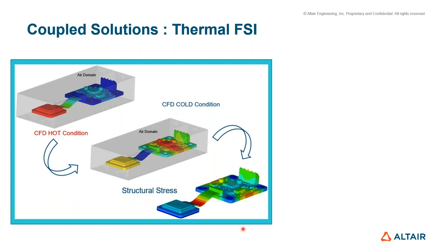Here you see I have a CFD model which has an air domain, and then there's a structure of the PCB board connecting with certain cables around the fingerprint location where you want to scan it. Now, this goes through a CFD, hot and cold conditions, followed by mechanical stresses in the end in order to calculate any kind of stresses for fatigue and various things. CFD is carried by AcuSolve. OptiStruct is taking care of the structural side.